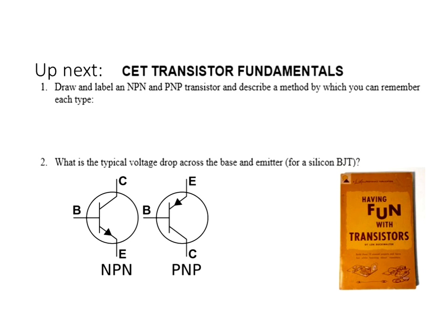What's a good way to remember if it's a PNP or NPN? I'm sure you heard this in class. Well, here's how you remember it. Look at this. This represents the diode between the base and the emitter. There's a diode in there. Turning that diode on makes the current flow. Turning that diode off shuts the current off in there. So, look, this diode is pointing outwards. A good way to remember it is not pointing in. It's NPN.